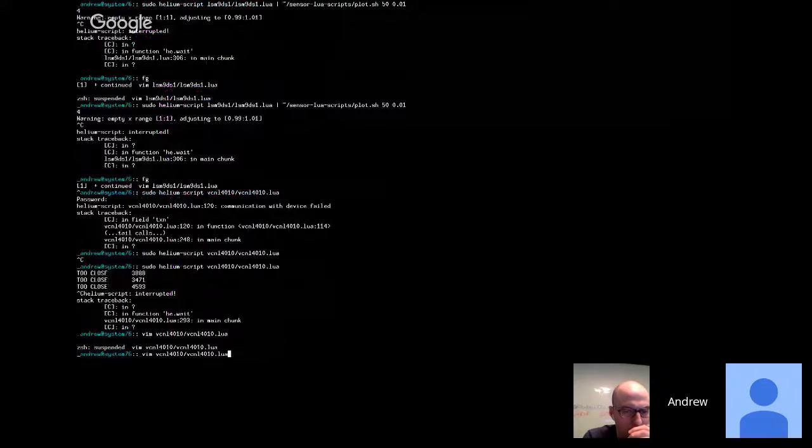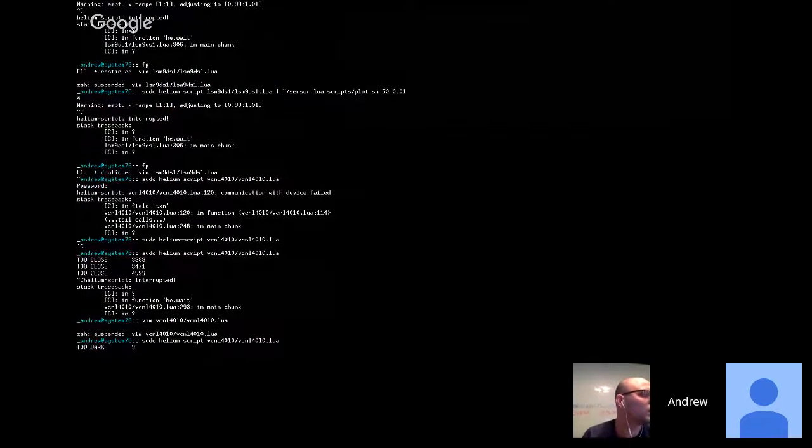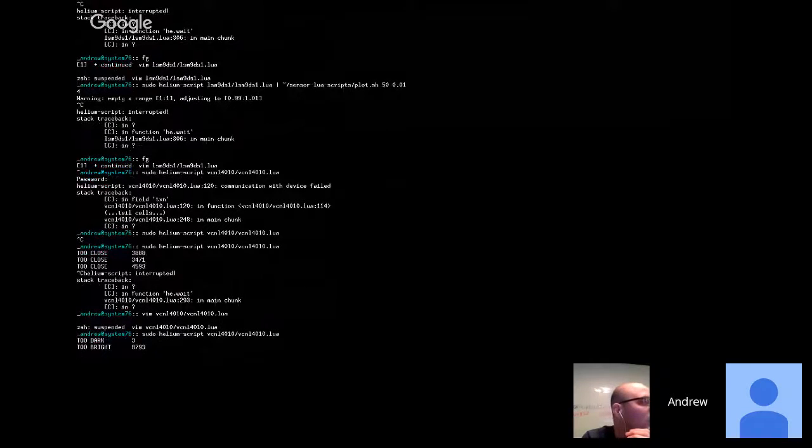So now if I cover up the sensor, it's going to tell me it's too dark. See? And if I put it right up next to this light bulb, it hopefully will say too bright. See? Because you can interrupt on high or low conditions. Interrupting on low proximity was so noisy I turned it off, but it shows the idea, and now it's just ambient, so it's fine.